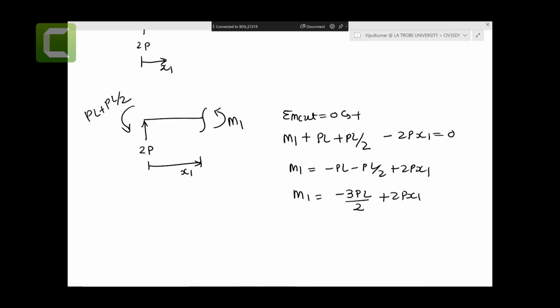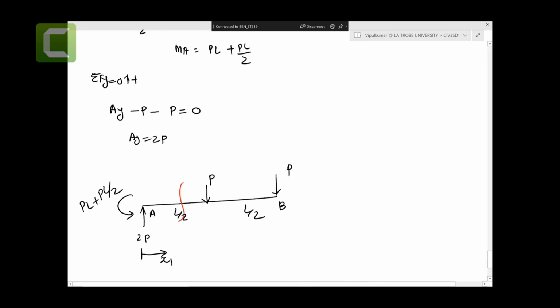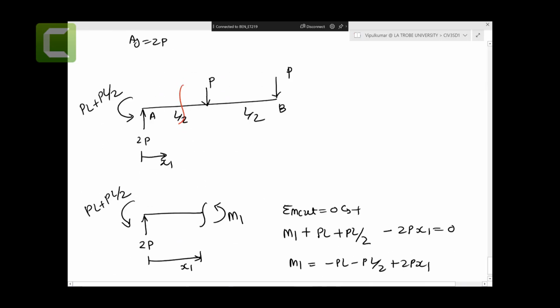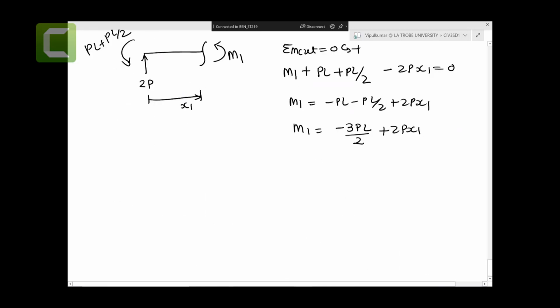We've done this kind of example plenty of times. You know, drawing the bending moment diagram, shear force diagram, making cuts and finding these M equations. Even in week number 5 in the elastic curve equations, we did that. So therefore I go fast here, and then you make another cut here at a distance of x2. So here we got P, distance x2, and M2.